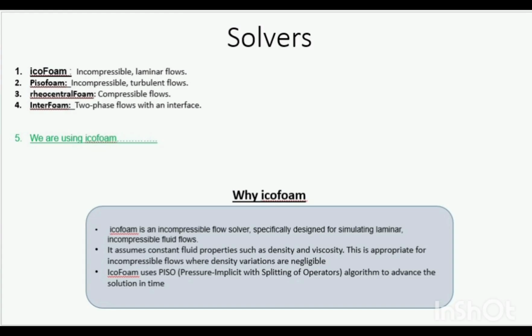It assumes constant fluid properties such as density and viscosity. This is appropriate for incompressible flow where density variations are negligible. icoFoam uses the PISO, pressure implicit with splitting of operators, algorithm to advance the solution in time.